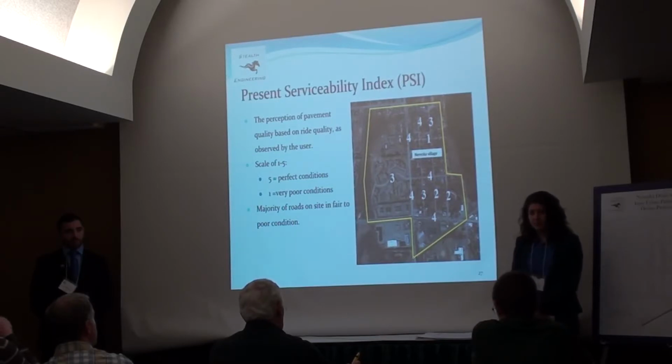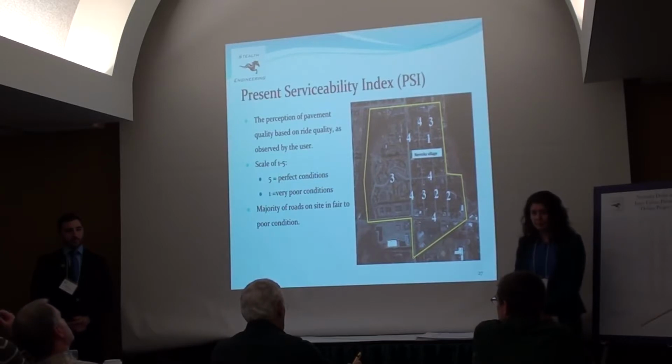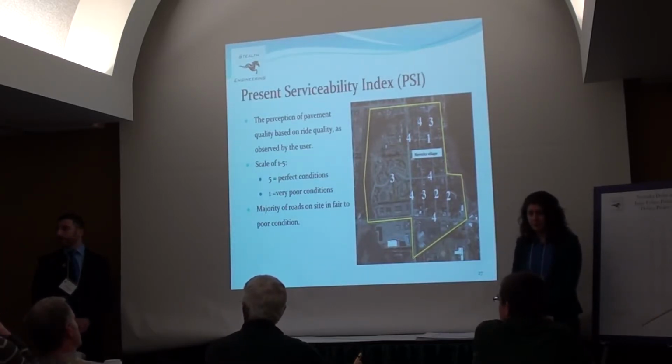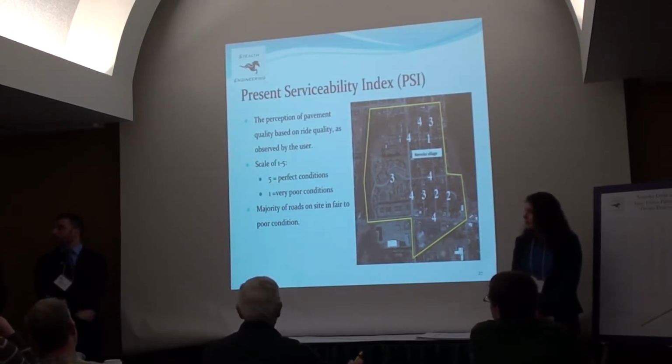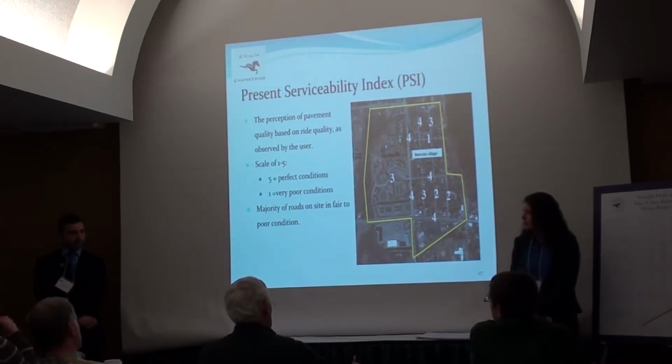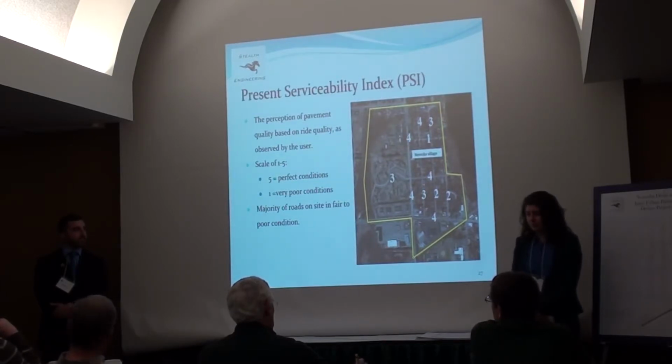So how did you decide, as far as your treatment, your overlay, how was that determined for the neighborhood roads? How was the thickness determined, or how did you determine that's what you needed, an overlay? That was based on AASHTO design. I determined an overlay was needed because of the stresses on site, just going out there and evaluating. Also based on thicknesses and age of the pavement.